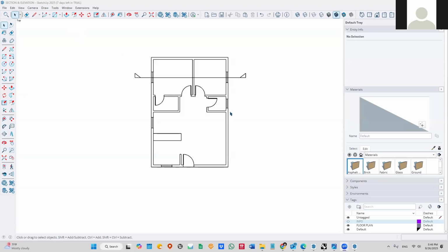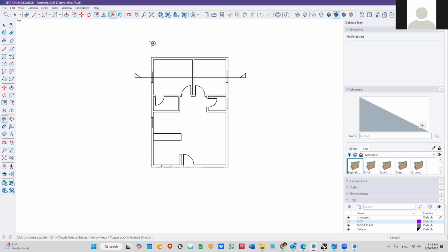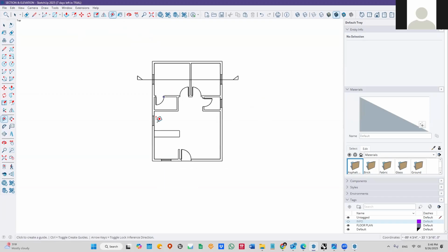All right. I'm gonna use guidelines to draw and create sections. As you remember, we had guidelines to create our floor plans last time. So again, type or select T on your keyboard and you get the tape measure, or T, to create your guidelines.